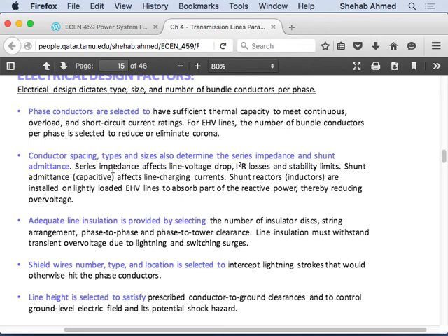So from an electrical circuit perspective, this capacitance, as soon as you connect it to a voltage, has to be charged. So there are line charging currents associated with charging these capacitors. These line charging currents are leading in power factor, right? We talked about leading power factor and how it affects the voltage of the power system. Leading power factor refers to positive reactive power being pumped into the system. Positive reactive power being pumped into the system leads to voltage rises in the system.